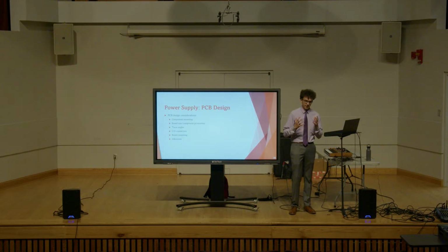You have to worry about the size of the board, how much space it's going to end up taking when you finally implement it in your case or whatever you're going to put it into, and how close you can get these components to each other. So for the power supply, that wasn't a terrible concern, but for analog sound generation circuitry, when you're running really high frequency information through these traces, you can only have them so close to each other before they bleed into each other, which is undesired.